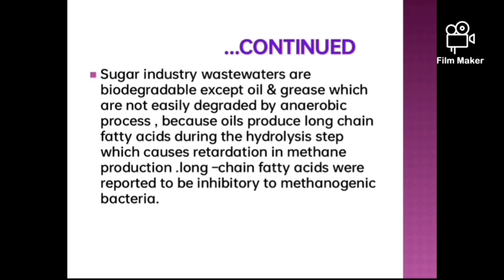Sugar industry wastewaters are biodegradable except oil and grease, which are not easily degraded by anaerobic process because oils produce long chain fatty acids during the hydrolysis step, which causes retardation in methane production.